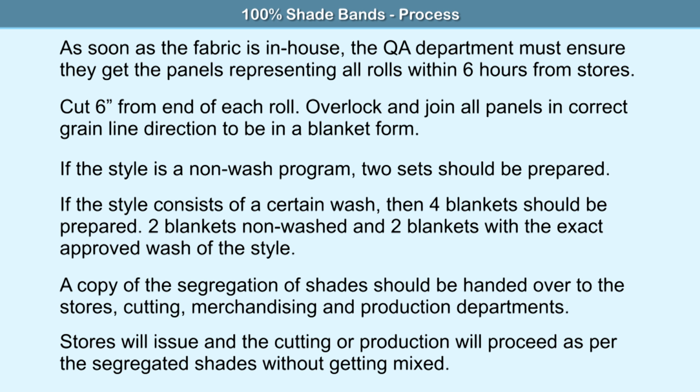A 100% shade band covering all rolls and all colors pertaining to a certain style or consignment should be made and approved prior to cutting bulk fabric.